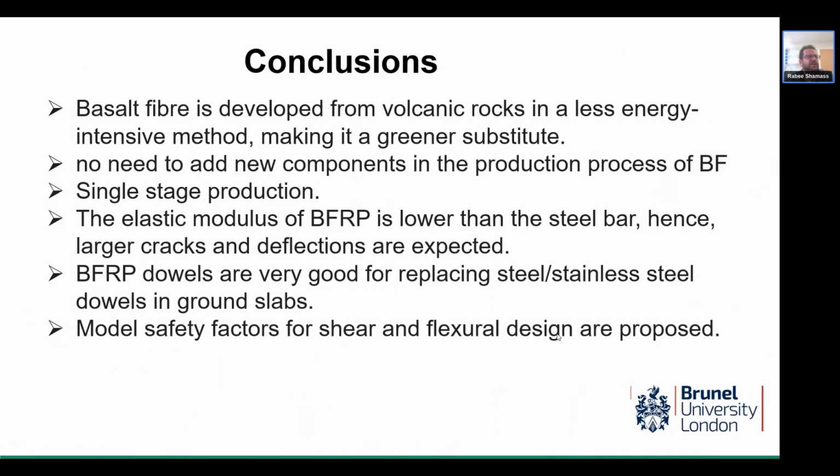And to produce the fiber, there's a single stage of production, which makes it easy to produce, not like glass or CFRP. The elastic modulus of BFRP is lower than for a steel bar, therefore there's going to be some cracking and deflection expected.